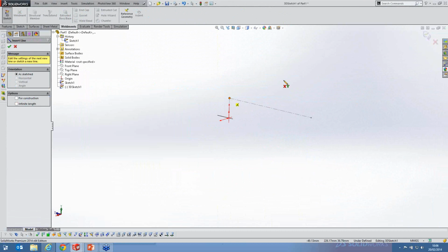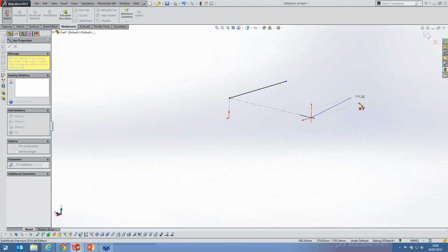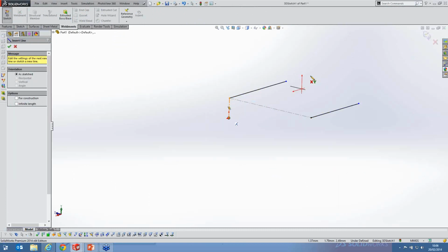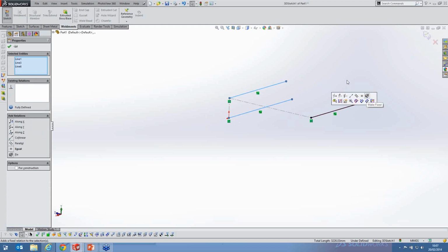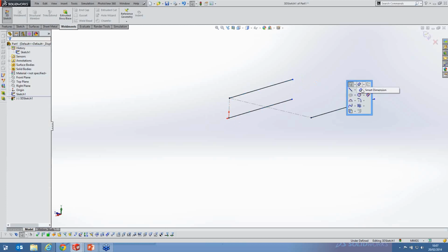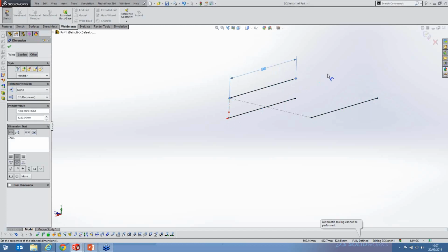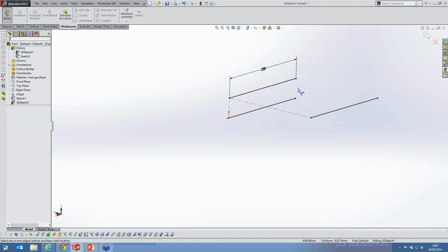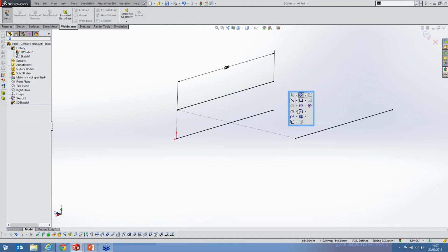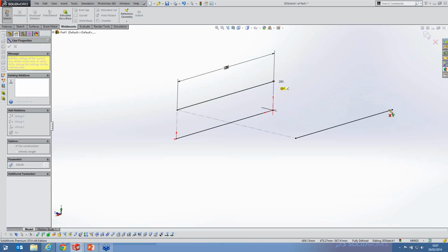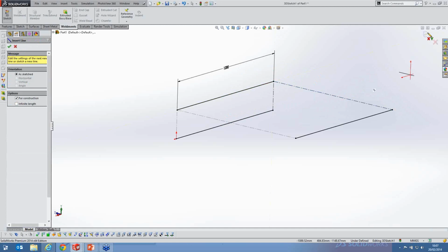We're actually wanting to position some bits of steel just to create our framework here. So I'm just using the sketch tools just to draw out 3 lines. I can make those all equal in terms of their length using the relationships, and then give those a dimension that I want to use there, like so. And I can connect those up at the other end if I need to, just again by using the very simple sketch tools within the system.